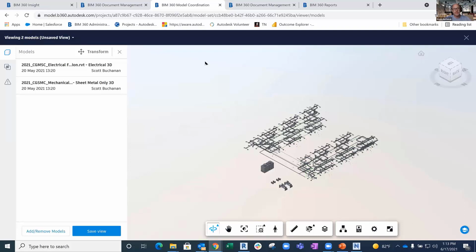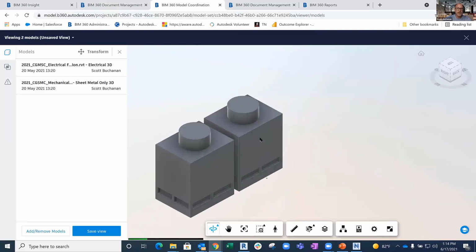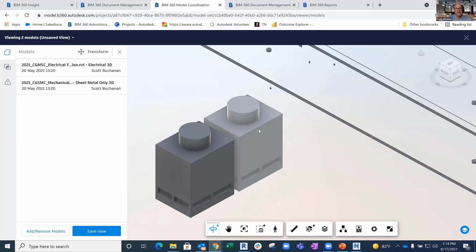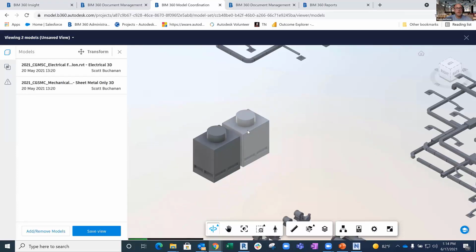And the reason for that is it's not on our side, it's just how those products write to an IFC file. They don't use the same element ID every single time it creates an IFC. So for example, if I was using a non-supported product that writes to an IFC, when they spit out this cooling tower, it may be element ID 12345A. Well, the next time they export an IFC file, that would rewrite to a completely different number. So that causes problems inside of here, because we're attaching issues and behavior to a unique identifier. So that's one of them to just keep in mind.